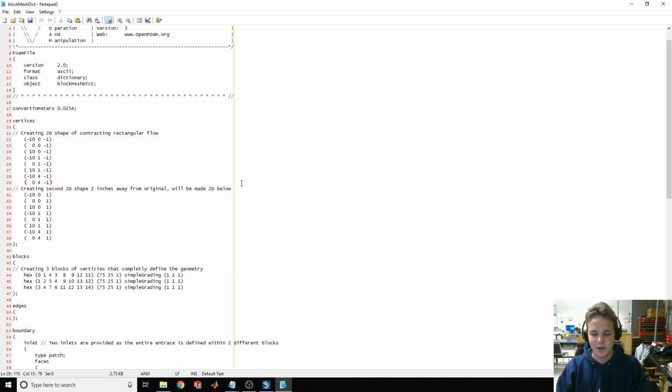So with any simulation, finer mesh can help, but it needs to be done right. And it also can take a lot of time. If I increase the amount of cells by 10, the time would increase by 10. So that's basically why we keep having to make sure that, yeah, this is a fine enough mesh where we still get accurate results. So you have to understand that. That's part of the engineer's job, is to understand how fine does it have to be to be accurate enough.